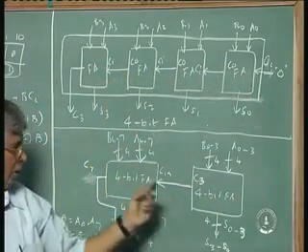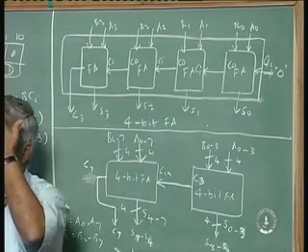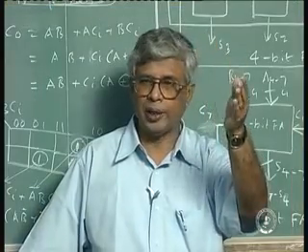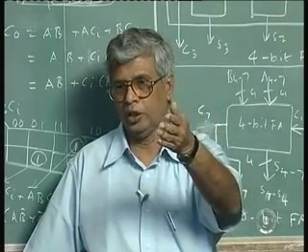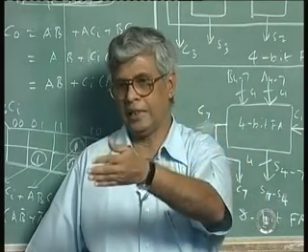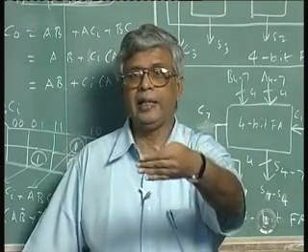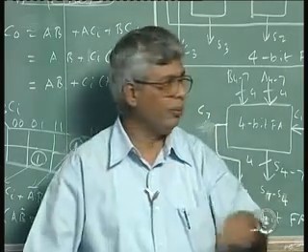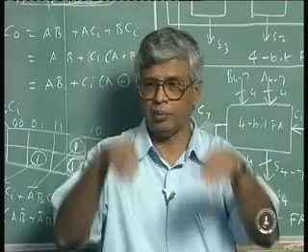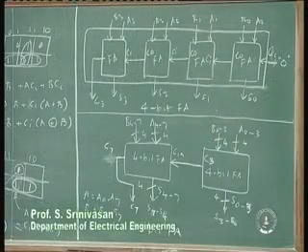The carry has to go from here to here, here to here, here to here, and then from here. So for the 16-bit full adder, which I asked you to do as an exercise, carry has to propagate through 16 stages. The first stage has to go into the second stage, the second to the third, finally it goes to the 16th stage. So 16 carry delays have to be accounted for. Meanwhile the sum will come, because as soon as A and B are known, the sum can only come once the carry comes; the carry triggers the sum. It's something like a domino effect.